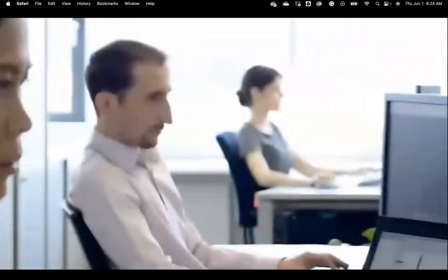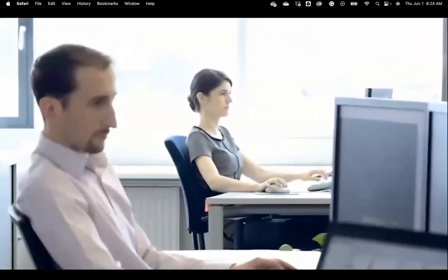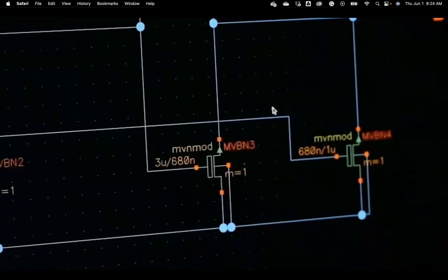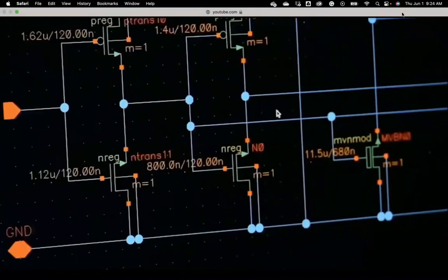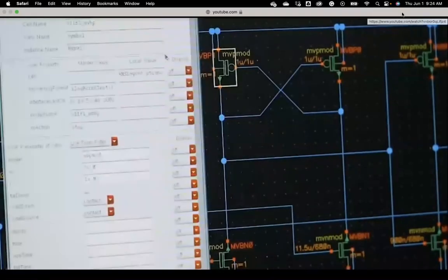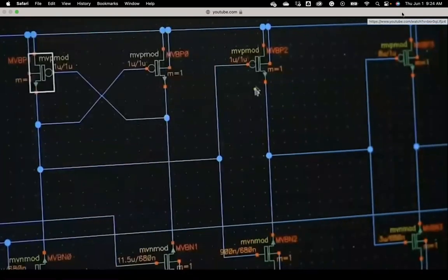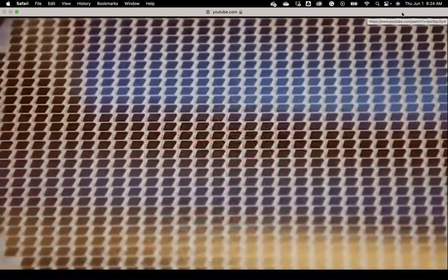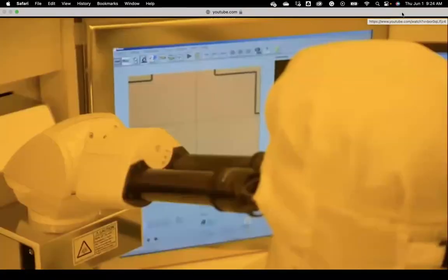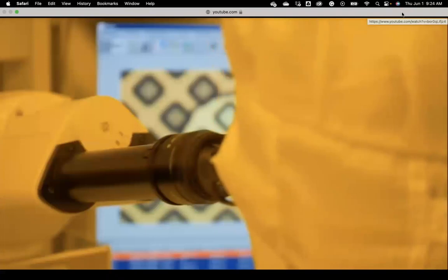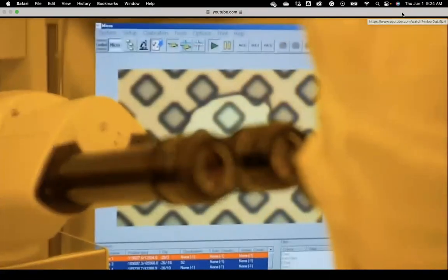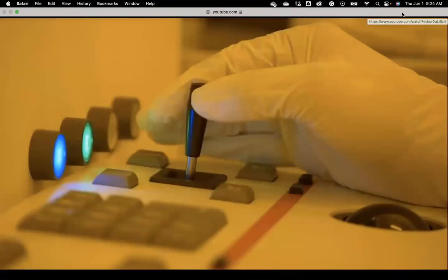The sheer number of components calls for an in-depth design process. This entails defining the chip's functions, simulating its technical and physical properties, testing its functionality, and working out the individual transistor connections. Special design tools are used to draw up the plans for integrated circuits and develop a three-dimensional architecture of sandwiched layers. This blueprint is transferred to photomasks. Providing geometric images of the circuits, the photomasks are used as image templates during the subsequent chip fabrication process.